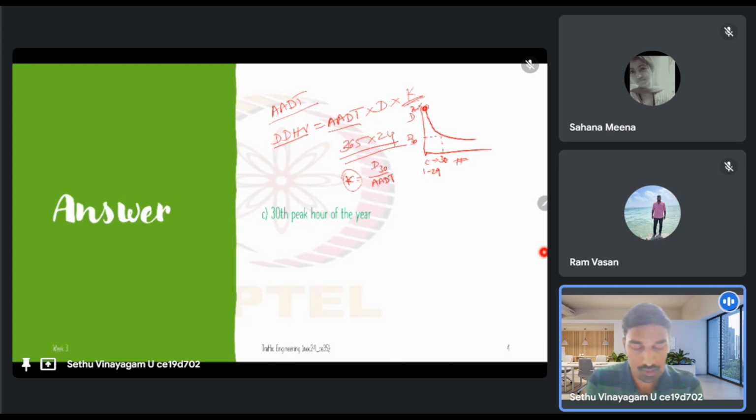Because it happens very rarely, if we design our facility for that D max, it's basically a lot of wasted resources for most of the year. The demand will never be equal to the capacity that we are going to use. Which means the facility will be over designed. So that's why we do not always go for the absolute maximum that we are observing.